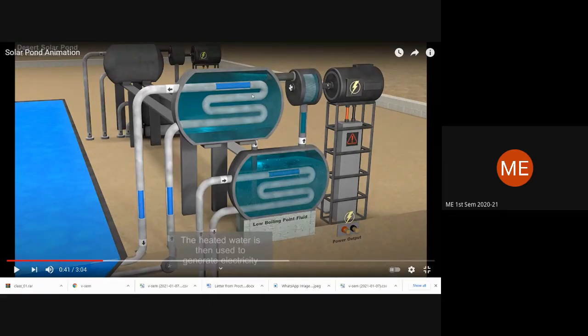Whenever these two interact, what will happen? The steam will get condensed, meaning it will convert from vapor into liquid. That liquid will be collected at the bottom, and the water coming out from this chamber gets heated up, not more than 35 degrees, about 5 degrees of rise, and it will flow to the top surface. The evaporated steam of the organic fluid will be condensed into liquid form and sent back to the evaporator chamber.